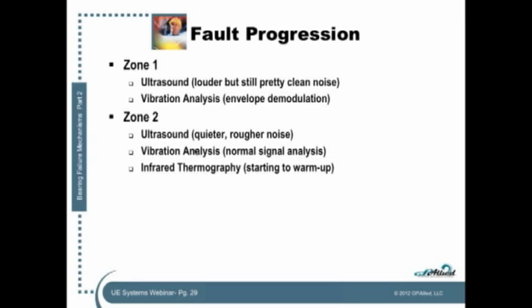In zone 2, the bearing is starting to warm up. Early in zone 2, it's just maybe a few degrees, but by the end of zone 2, it's a significant increase in heat, and it's easy to tell that the bearing has an increased level of friction inside of it due to the spalling and the balls bumping in and out of the holes created, the spalls, right? So starting to warm up.